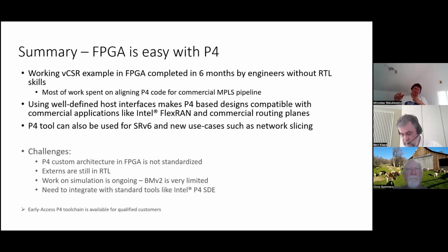We operate on the level of packets. You can use any kind of DMA, custom DMA, whatever, as long as it is able to send and receive packets with the interfaces inside of the FPGA, connected that way with our P4 pipeline, fully generated from the P4.